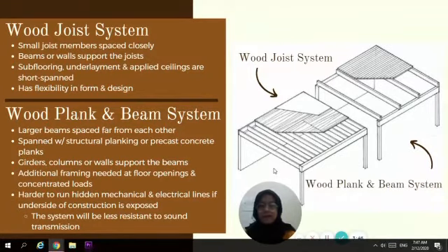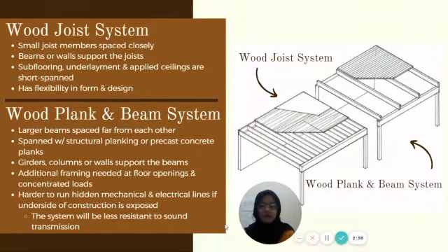And the wood plank and beam system requires additional framing at the floor openings and at places where the loads are concentrated. And if the underside of the construction is exposed, it's kind of hard to put hidden electrical or mechanical lines underneath because it's exposed. And because it's exposed, the floor system will be less resistant to sound transmission.